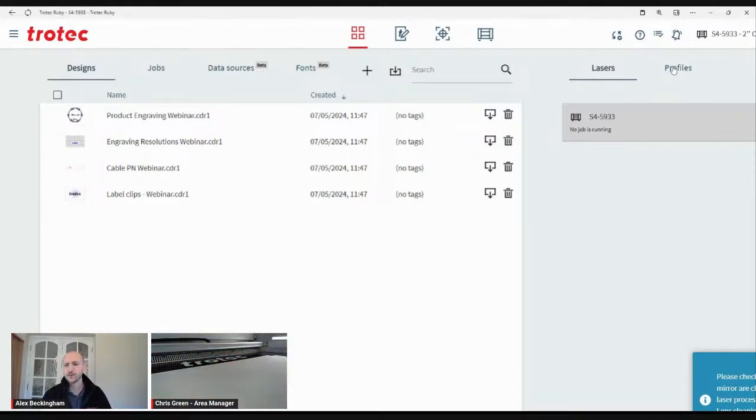So I've just seen again in the comments about double cut lines. It won't automatically be turned on if you don't have it set in your default settings. Normally the double cut lines feature will be turned off, but you can go into your settings and turn that on, or you can manually turn it on for each job. So just check that before you run the job. That might be why you still saw some double cutting.